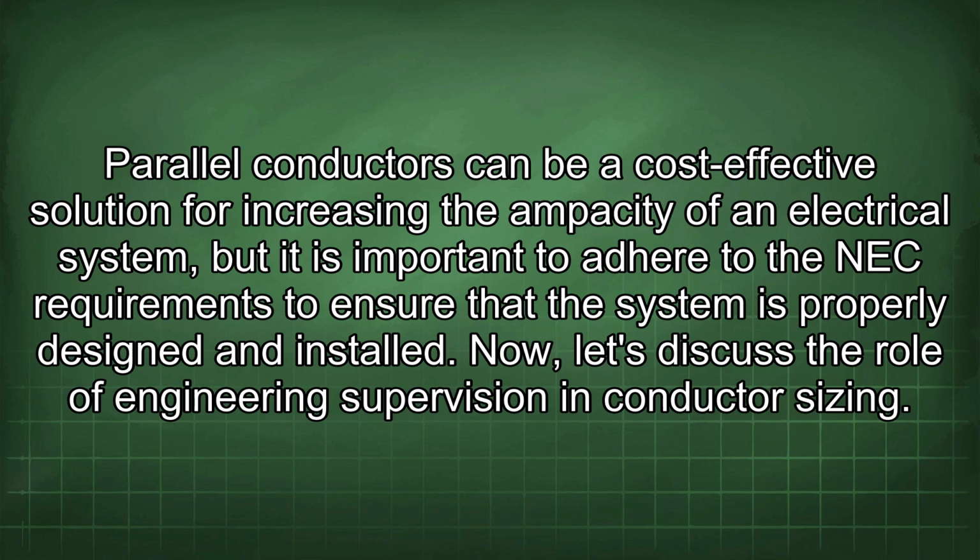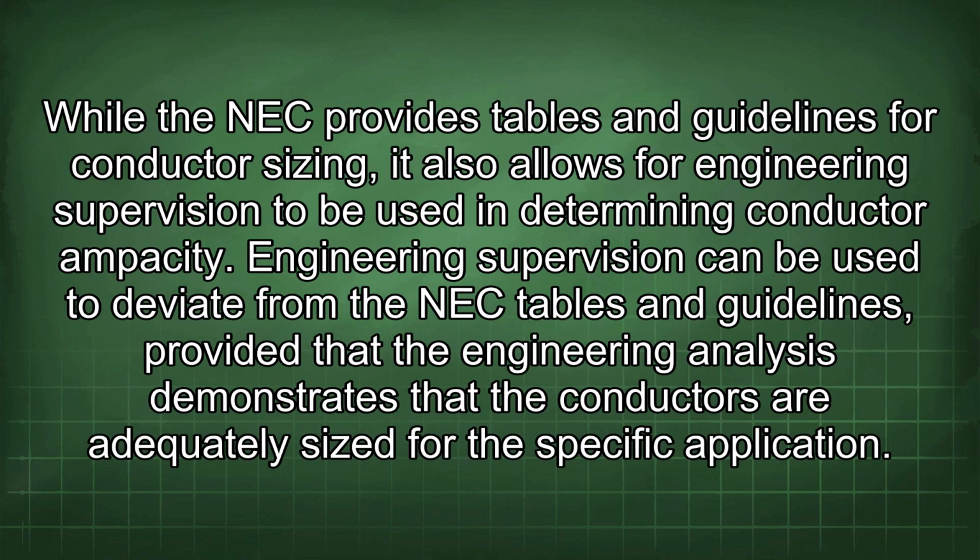Now let's discuss the role of engineering supervision in conductor sizing. While the NEC provides tables and guidelines for conductor sizing, it also allows for engineering supervision to be used in determining conductor ampacity. Engineering supervision can be used to deviate from the NEC tables and guidelines, provided that the engineering analysis demonstrates that the conductors are adequately sized for the specific application.